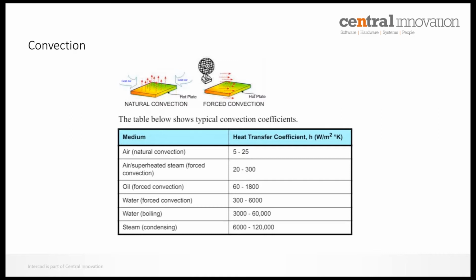To give you an example, if you approximate or assume your models which you study are undergoing only natural convection, you could use a heat transfer coefficient value between 5 to 25. So why is there a range of values? Basically, sometimes the model you study could be located inside an enclosed chamber, something like a computer CPU or computer casing. Therefore, the air domain is quite confined and it's not as large as compared to the situation where the component is completely exposed to air, as in it's sitting outside exposed to an infinite amount of fluid domain. Therefore, you could use values ranging from 5 to 25.